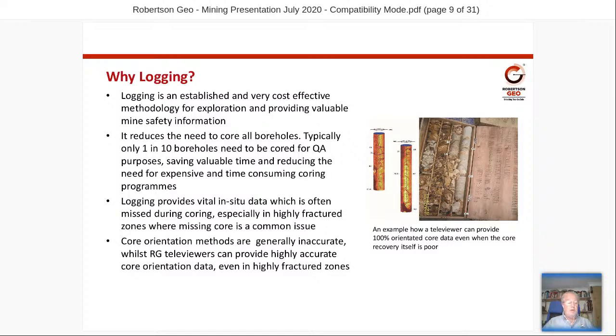And quite often with coring, depending on your subsurface conditions, you may end up with a core that looks like the image on the right, where we have a severely fractured section of core, which is basically crumbled and consolidated. And in that case, it would be extremely difficult to detect any fractures, any structure, any bedding planes in the core. So where you have very poor core recovery, logging provides vital in situ data, especially in highly fractured zones.